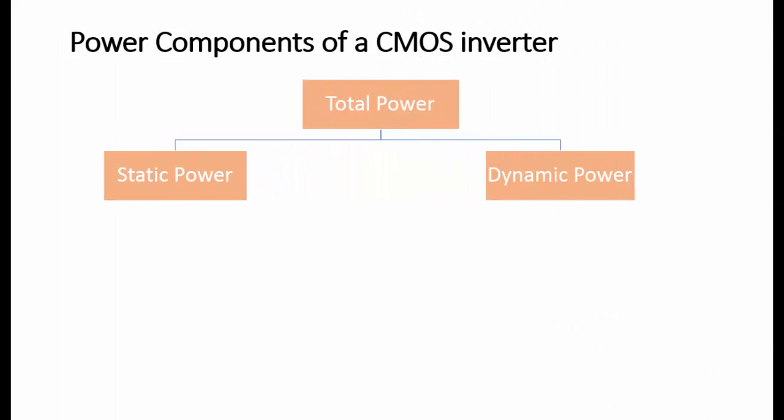In general, most devices have very low static power consumption, which happens when the transistors are in off state. It occurs when all inputs are held at some valid logic level and the circuit is not in charging states. But when switching at high frequency, dynamic power consumption can contribute significantly to overall power consumption, and it happens when transistors are in on state. Charging and discharging a capacitive output load further increases this dynamic power consumption.